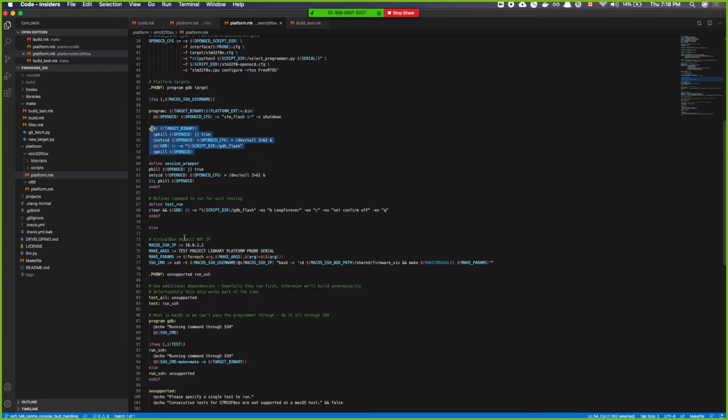And GDB will help me a lot there, because in GDB you can do really cool stuff, such as read, as the application is running, any place in the memory, like what the value is. And you can also write to any place in the memory. So I was able to manually make an LED blink by just writing to this register that was mapped to my memory. And that was pretty cool to me, because I was like, holy shit.